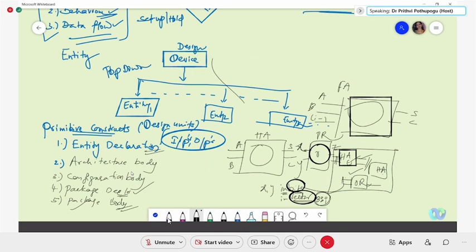Entity defines the netlist that is available for the user. Entity declaration will give only the netlist of the inputs and outputs. This never speaks of what is the hardware internal, and architecture speaks of the hardware. And the configuration body speaks of how this hardware you are defining here are related to each other.